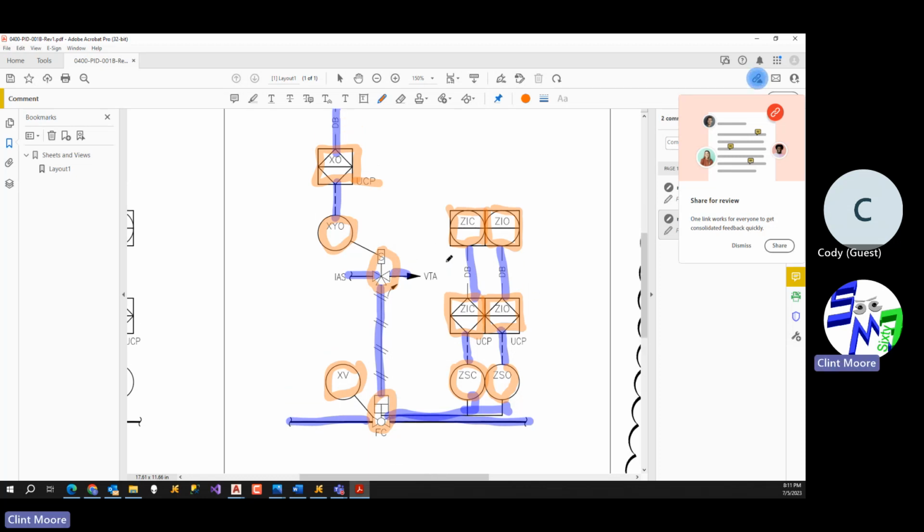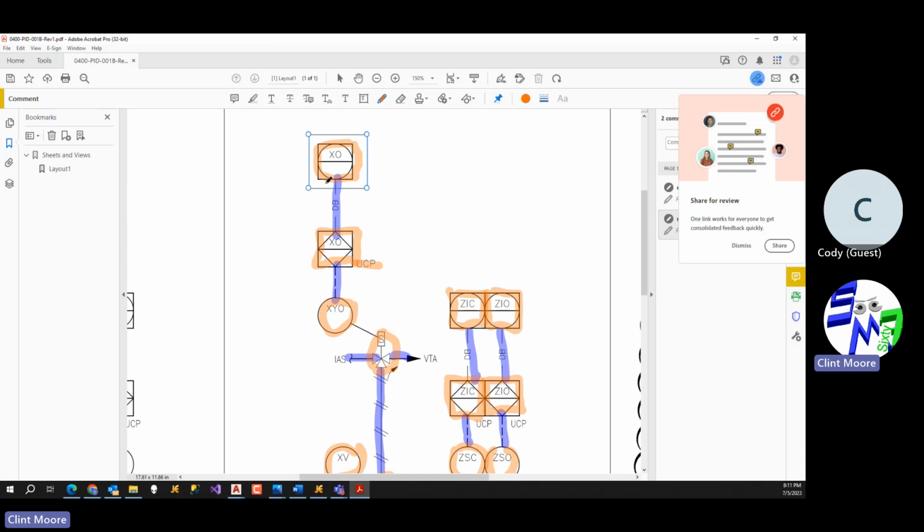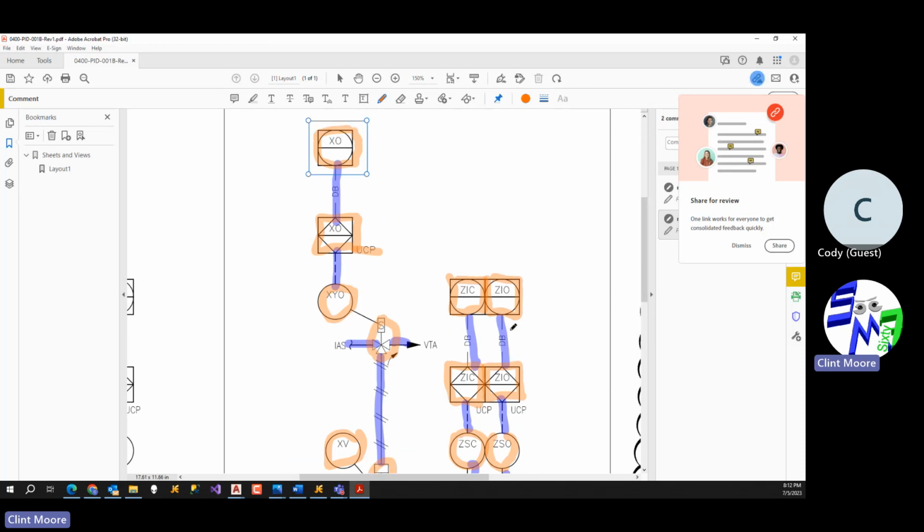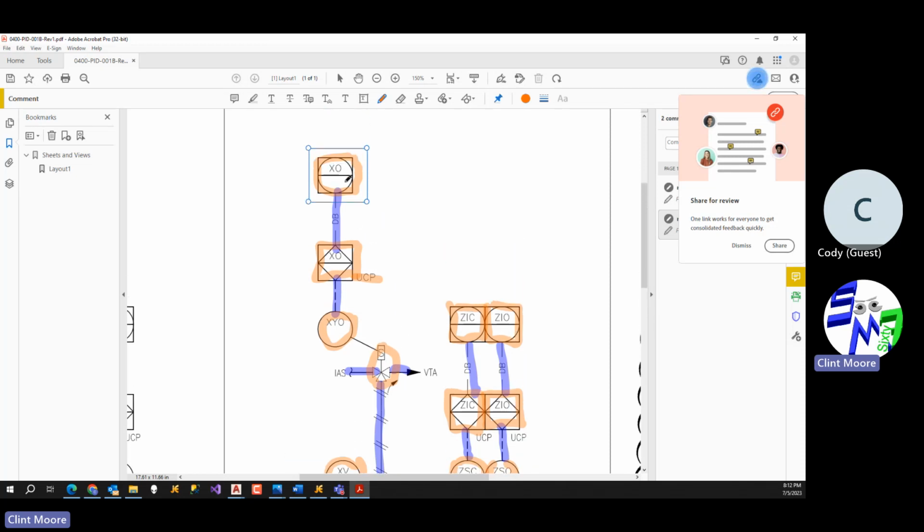So to build this, you need to have some layers that have these line types in it. Okay, and you can create line types that actually have letters or characters embedded in them. You can also have line types that have dash or crossing lines like this here. And you can also have lines that are a little thicker. We've worked with those using P lines, but you can also use a color table on your plot style to actually control and make this pen width here thicker. We've gotten into a little bit of plotting before, but we're going to stay away from that for right now. We're going to talk about these symbols.